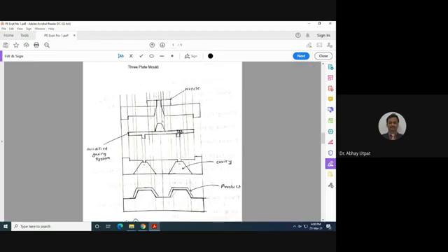And similarly, the plate will open 2 times. Once it opens, the gap between first and second will let the runner system, that is the gating system, come out, and the gap between 2 and 3, that is where the product will come out, and the ejector mechanism will be somewhere here. That we have not shown here now. So you can take a screenshot of this 3-plate mold.